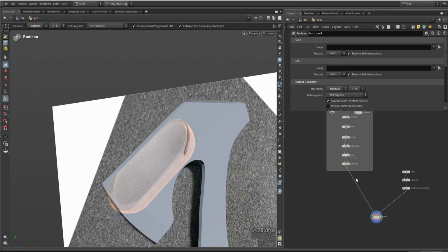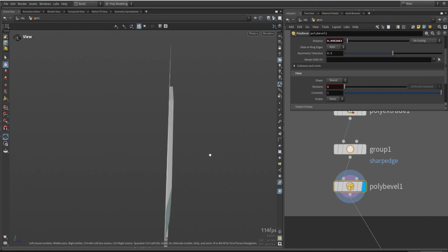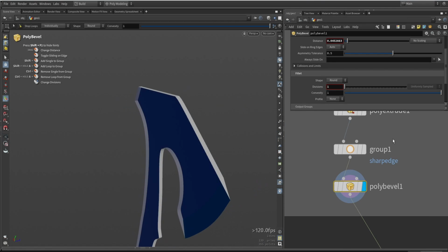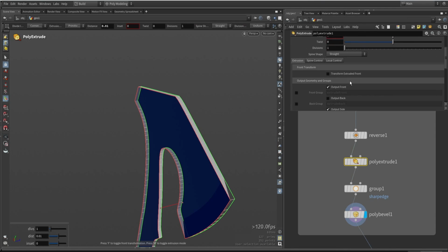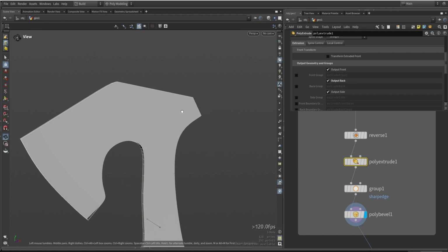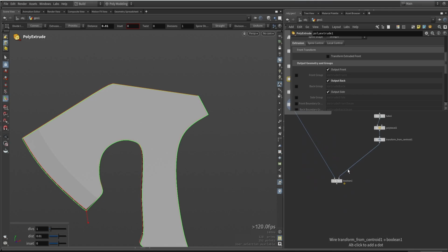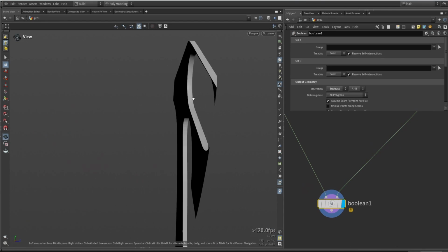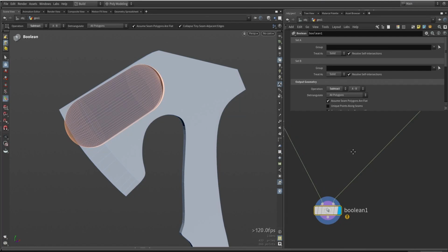Now, one thing that I noticed here still is that actually my shape is probably still open. So here on the back side, it's an open 3D model. In my extrude node, I can actually enable here the output of the back, so it will make it into a closed 3D shape. So that will actually help us a bit when we're doing subtraction. So you can see we're already subtracting the shape and a big cutout has been made.